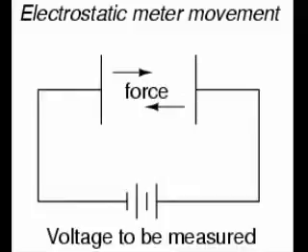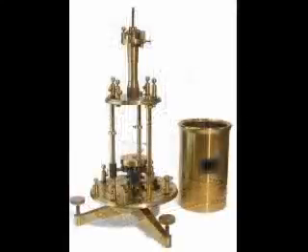That physical force is directly proportional to the voltage applied between the plates, and inversely proportional to the square of the distance between the plates. The force is also irrespective of polarity, making this a polarity-insensitive type of meter movement.